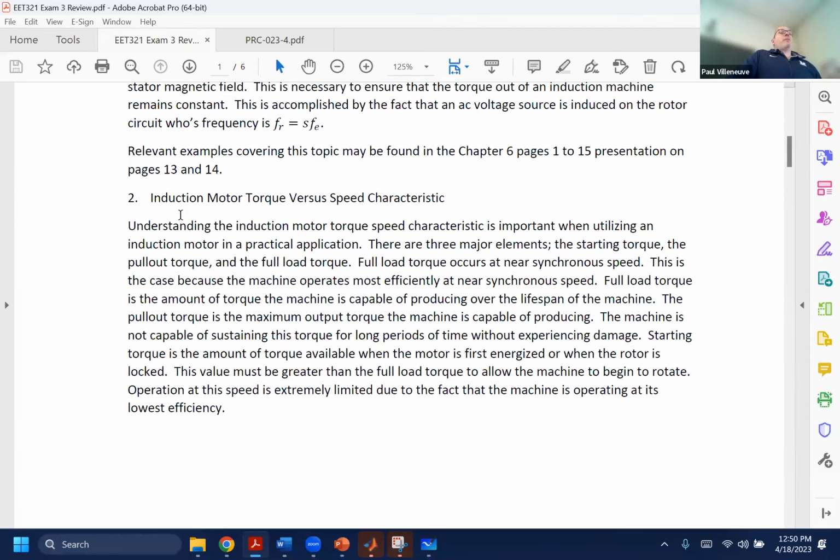And as an electrical engineer you just come up with general design parameters, saying, I want it to be able to run at a 1.15 service factor. I want the power factor to be a certain value, the electrical parameters, but the actual torque versus speed characteristic is more of a mechanical parameter. The only time I've seen actual torque versus speed characteristics is at nuclear plants, where they have very detailed studies looking at the speed and trying to figure out what happens with the pump and all these different things, because they're trying to calculate load. Those are the only times I've actually seen them, but I'm sure they're available. And if we have the impedance data, we can actually come up with them ourselves.